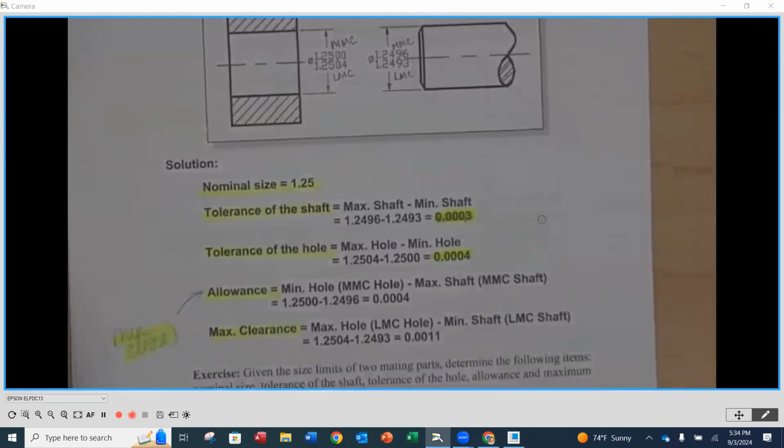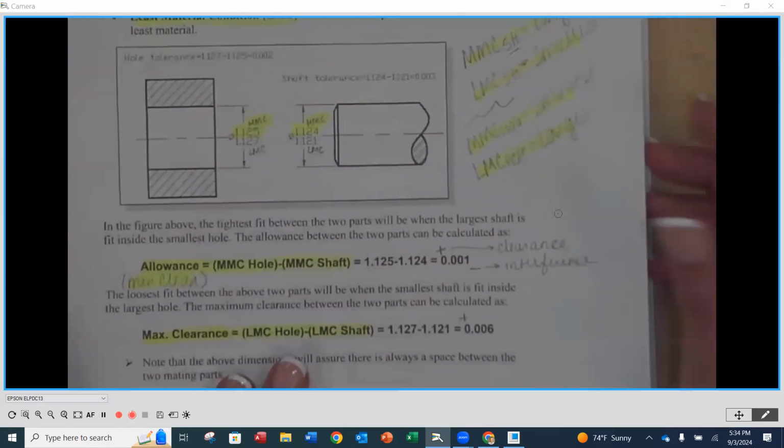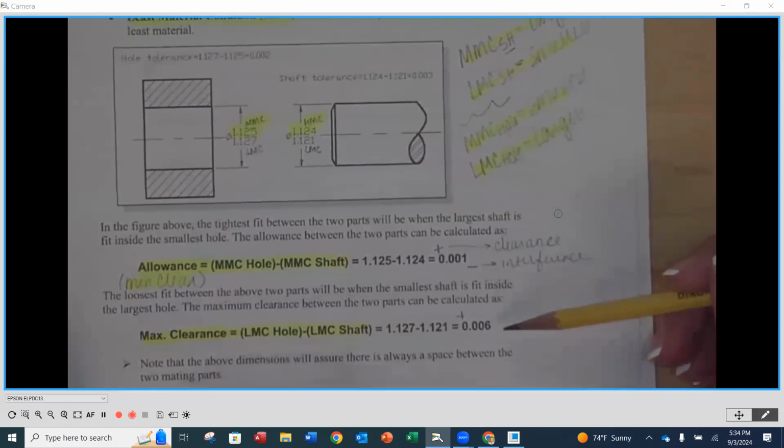I would say you're taking multiple passes to get to these values. You aren't going to just do it in one pass, whether it's a drill or even, you're going to probably put a boring tool in there, maybe even ream it. So yeah, these are small tolerances as we're seeing them here. If we're looking at, for instance, on the previous page, where we're dealing with 1,000ths or 6,000ths, these are larger tolerances, but how would you consider those?